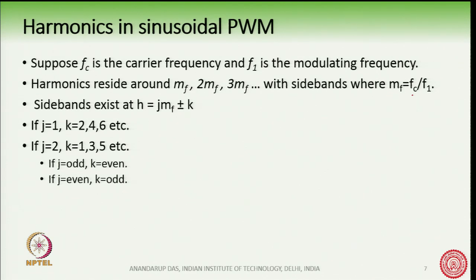So, mf. The harmonics in sinusoidal PWM reside around mf, 2mf, 3mf, like that. So, this is the position of the harmonics in the harmonic spectrum.